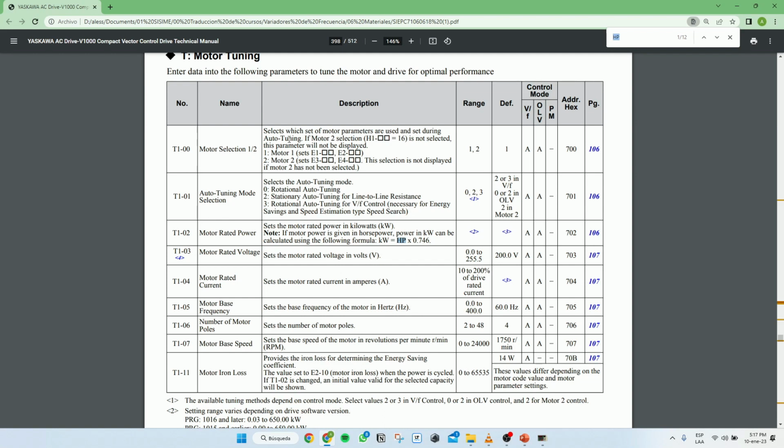So here for this part, for our parameters, for our motor adjustment, it's going to allow us to enter our nominal voltage for our motor. Remember that I told you that this is the additional optimization for that motor. This is where we're going to be able to enter it, and only for what our drive is going to allow us to do. Because if you say, well, you bought a 255 volt drive, so what's going to happen here? Well, we would be unable to change it to 400. We need to be very careful with this.